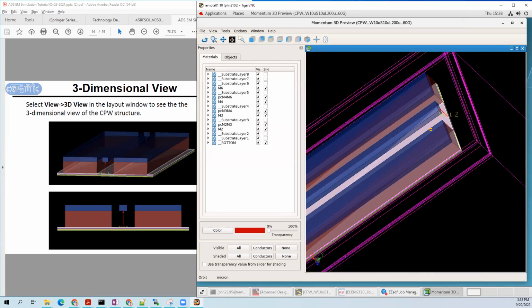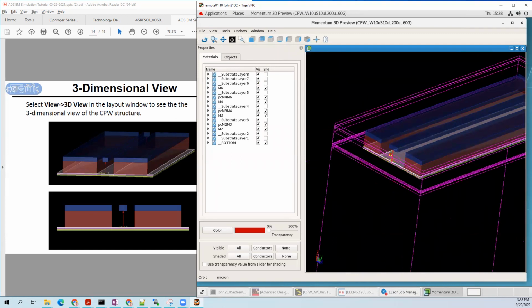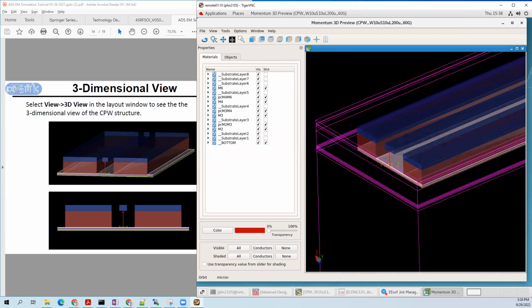Okay, thank you. So essentially, what is happening here is you can imagine that physically we attach a signal into the M6 and M2, and then we excite some VS here, and we measure IS, and from that we can capture the S-parameter behavior of this structure.